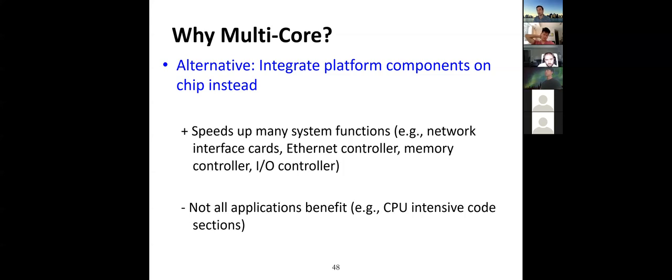All that said, one of the sub-teams of the Microsoft Azure Catapult project actually implemented the networking protocol. Think about TCP/IP purely in hardware. They took TCP/IP because that was their bottleneck. They didn't want to pay millisecond latencies for the access, because TCP/IP was essentially bottlenecked with some CPU-level code. And they just rewrote that protocol in pure hardware using FPGAs. So FPGAs are used like networking devices there, and they can go to microsecond latency instead of millisecond latencies. If you look at scale, like at the cloud, it might be worth doing, but for a single app, it might not be beneficial.